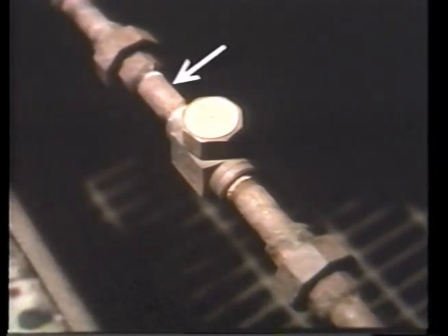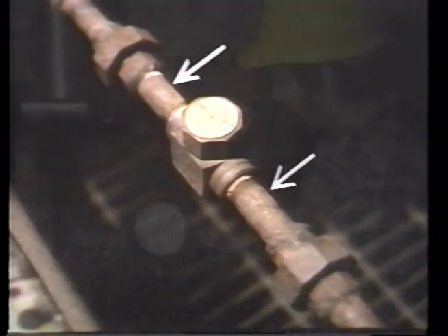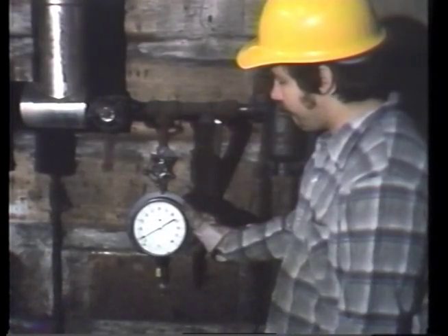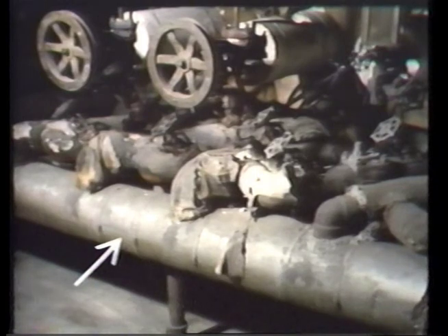Make sure the condensate line to the trap is large enough to carry the condensate that's being produced. The drip line to the trap should never be smaller than the trap inlet size. Similarly, the condensate return line from the trap must be large enough to carry both the condensate from the trap and any flash steam that is formed. Discharge lines should be at least as large as the trap outlet. Check the back pressure at the trap outlet to make sure it's not too high. If several traps discharge to a common return line, the line should be large enough to handle the discharge from all traps without developing excessive back pressure.